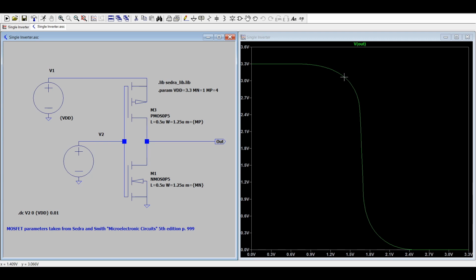The fact that we have such a steep transition, firstly, as I said before, is very important for noise robustness, suppressing noise effects. But it's also due to the fact that these channels can open up quite quickly. So we can go from a channel being very high impedance, well over say 10 megohms, to suddenly being quite a small resistance here opening up. And that rapid change in the resistance here, as we change the input voltage, causes this very steep drop here.